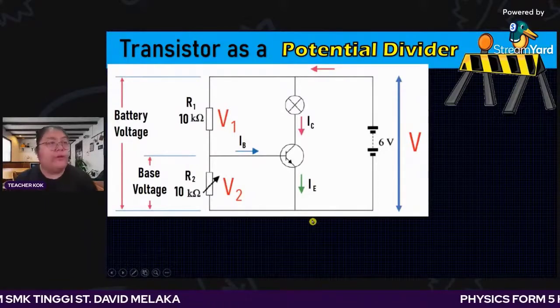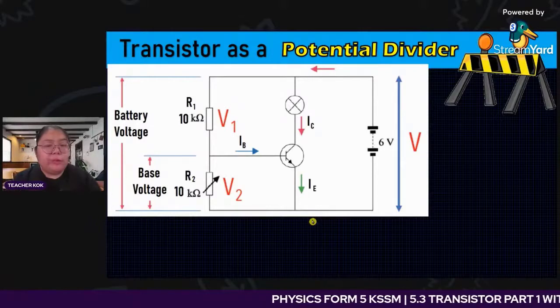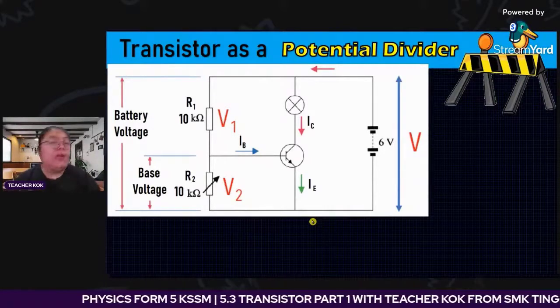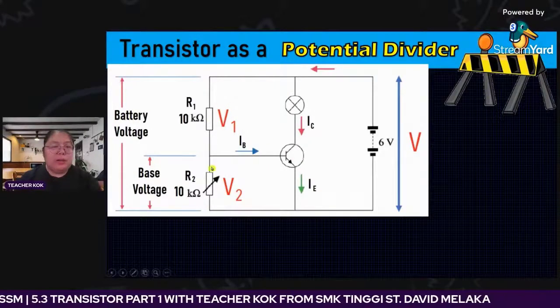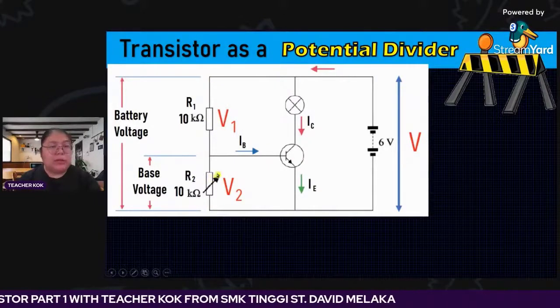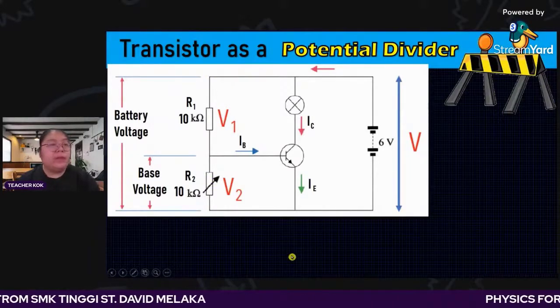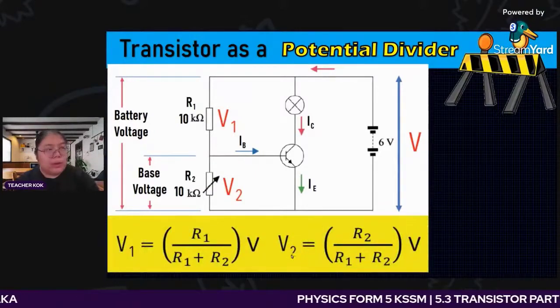Okay, there is a formula to let you do the calculation faster. In this situation, you do not need to find the current. Normally V equals IR, so you would need to find I. From here, R1 and R2 have the same current because this one is a series. But here, we never use the calculation for current. We straightforwardly apply the formula.